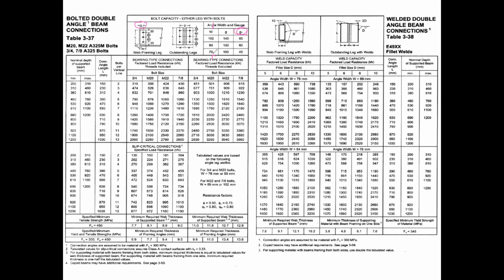And then of course, for the supporting, this is the gauge distance between the line of bolts, and this is what's recommended. This way, when you put them down, it will not interfere with that little fillet inside. When you put your washer down and your bolt down, you want to make sure you're far enough so you're on the flat part of the leg. So this is just to give you more information on how to detail your connection.